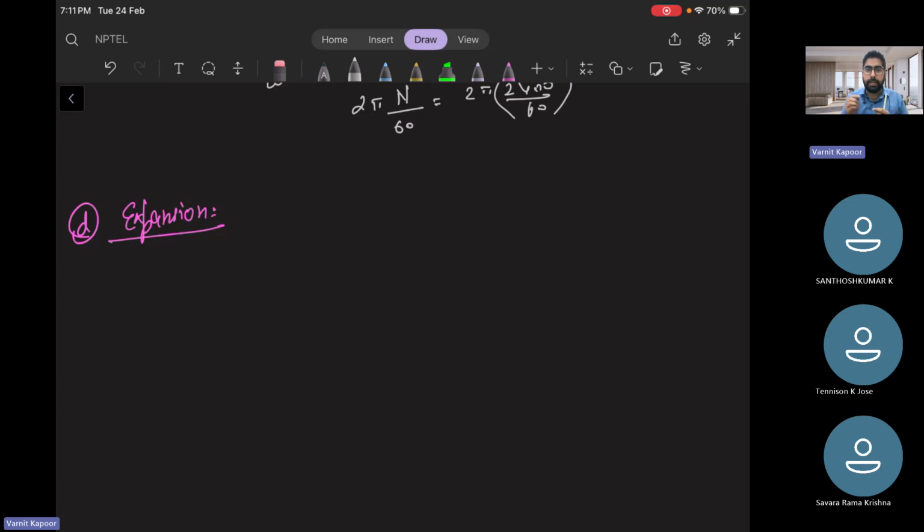Similarly, that heat being rejected is because water is taking that heat from the compression process, but the water jackets are still around the engine cylinders as well. So the same amount of heat extracted during the compression cycle, when the expansion stroke is happening and the temperature is dropping from higher to lower, that high temperature water will provide the heat back during the expansion process. So what will happen? The work produced will be lesser than the work produced in the ideal scenario.